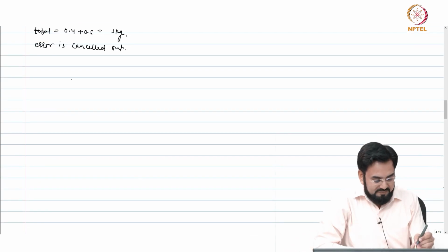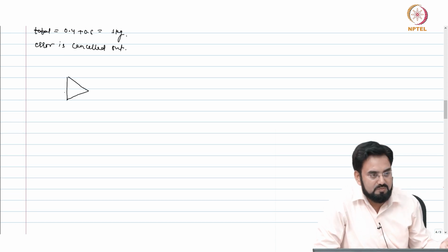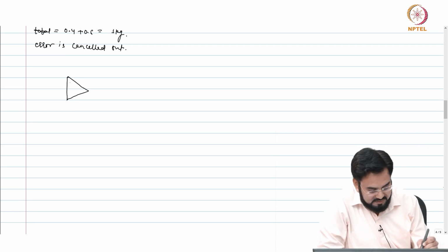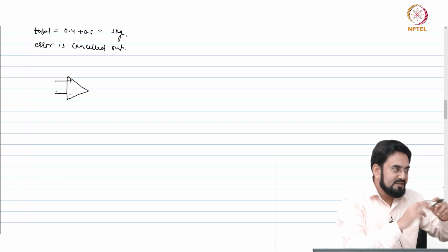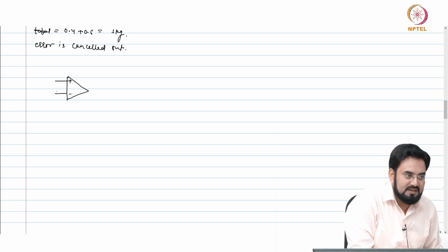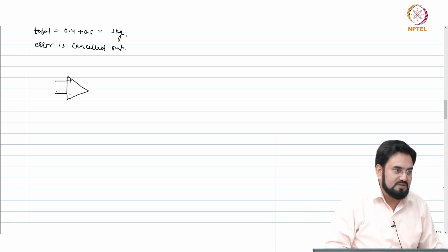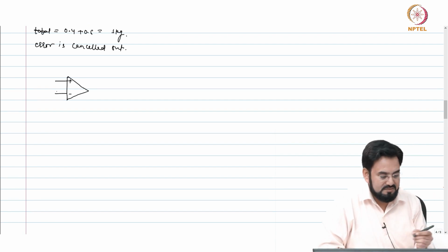So what you do in the amplifier, so each amplifier has 2 inputs and 2 outputs, positive and negative. Okay, and since I am operating in the feedback, I have to ensure that when I change the inputs, it should still be operating in the negative feedback, which means when you are changing the input, you have to change the output also, so that your negative feedback is maintained, otherwise this will not work.